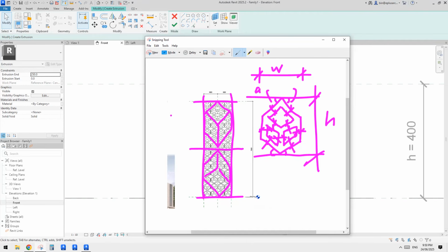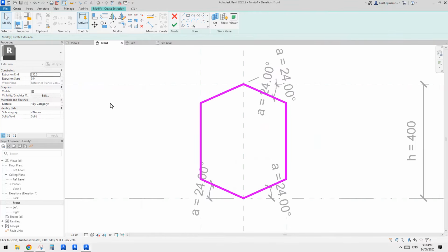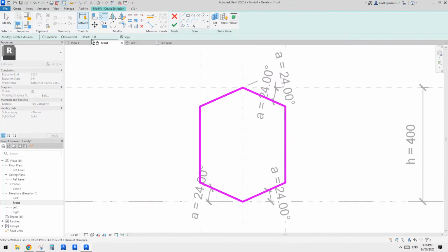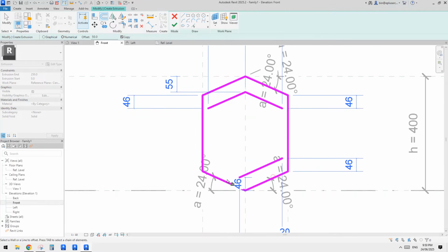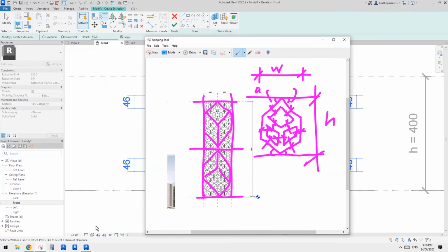these openings, right? So we're going to just use offset or just OF and then type in a number. Let's try 20, maybe a little bit more, 50. Yeah, and then just pick 1, 2, 3, 4. Let's have a look. We will need 1, 2. We need another one here. So we might need to control this one.